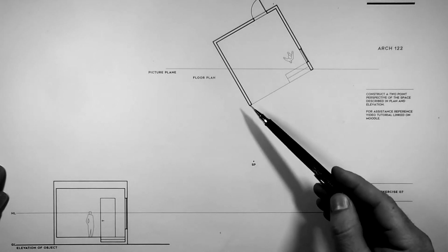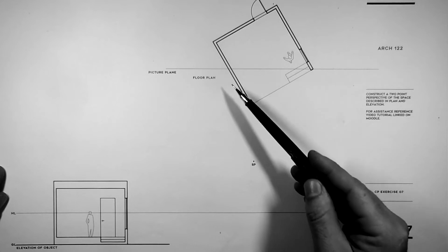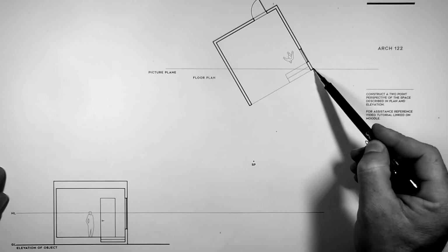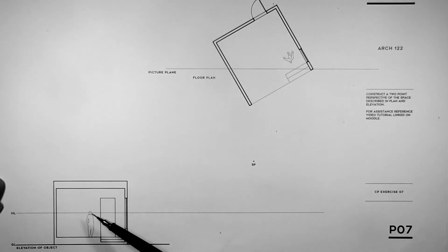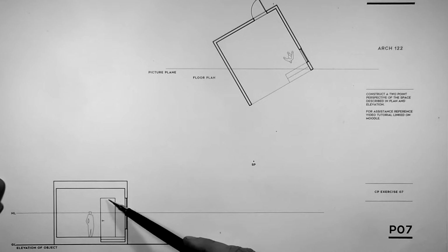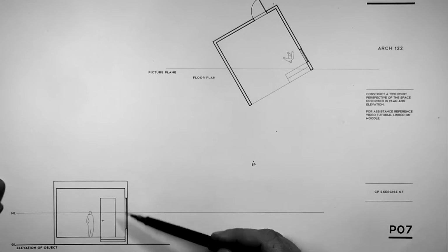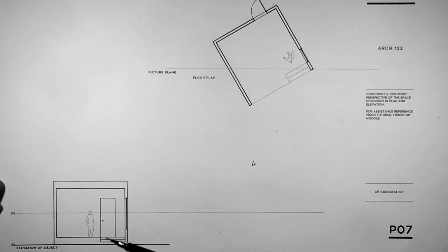It is rotated 30 degrees, so this is 30 degrees from horizontal, this one's 60 degrees. We have a picture plane passing through this right-hand corner, and then we have our elevation set up here with a horizon line at 5 feet above the floor, passing right through the eyes of our scale figure. And extending on, we've got a ground line. This is drawn at 1/8 inch equals a foot with an 8-foot door and a window head of 8 feet and a window sill at 2 feet above the finished floor.